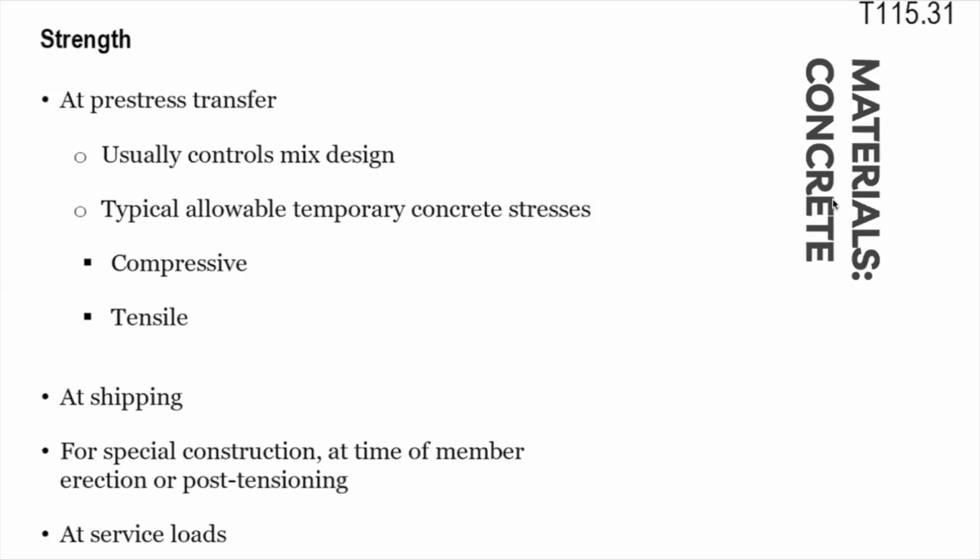So now we're going to talk about the concrete strength. The concrete strength for precast pre-stressed members primarily hinges on the strength necessary at pre-stress transfer, especially if transfer occurs shortly after casting, sometimes within 18 hours.